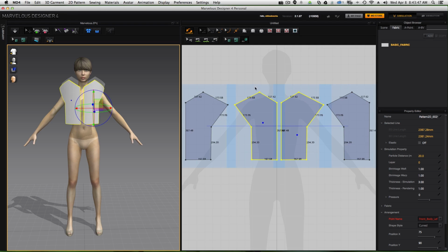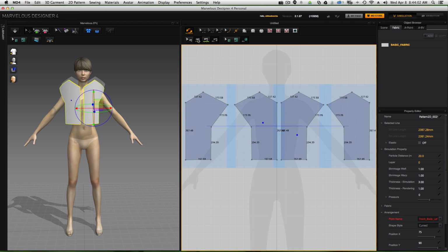Seams are simply the joining of edges between two patterns, a pattern and an internal shape, or two internal shapes. The first sewing tool is called the segment sewing tool. It's a sewing machine with a little straight green line under it. Segment sewing joins two edges, with each edge consisting of 2 points and a line connecting them. The lines do not need to be the same length.